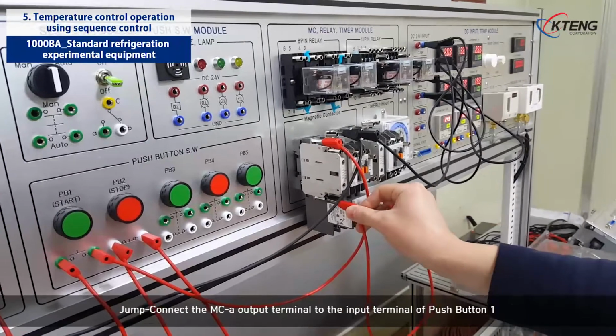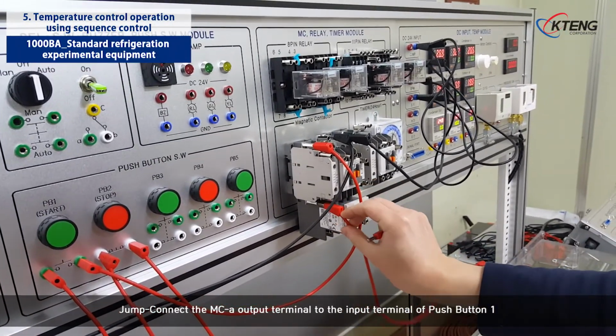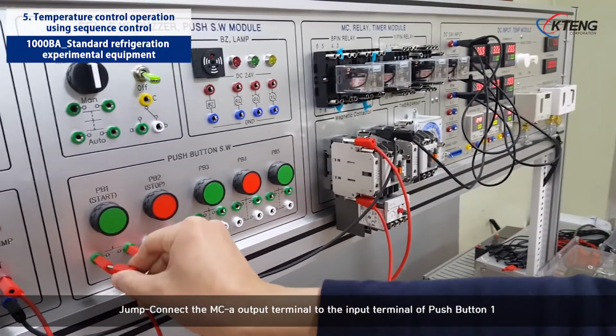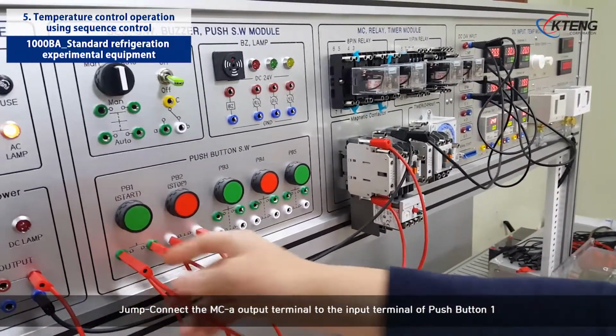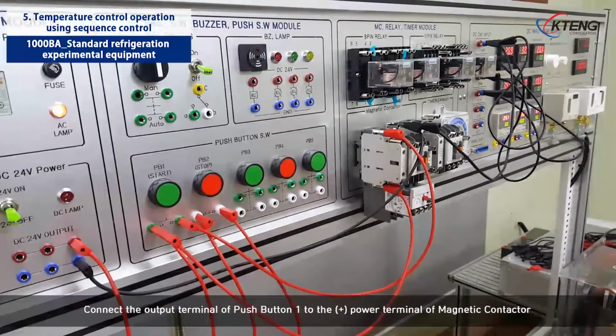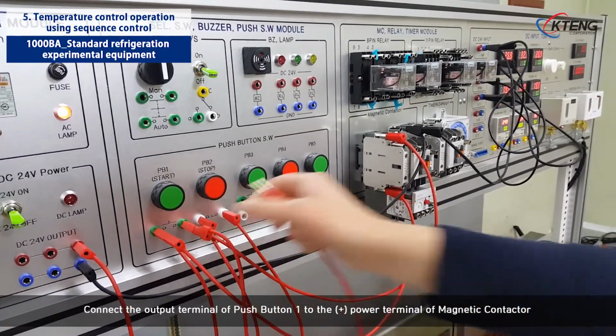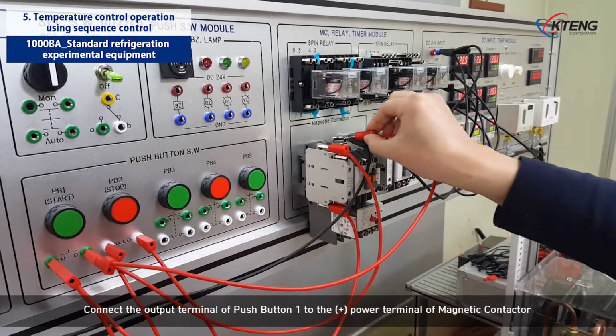Jump connect the MCA output terminal to the input terminal of push button 1. Connect the output terminal of push button 1 to the positive power terminal of magnetic contactor.